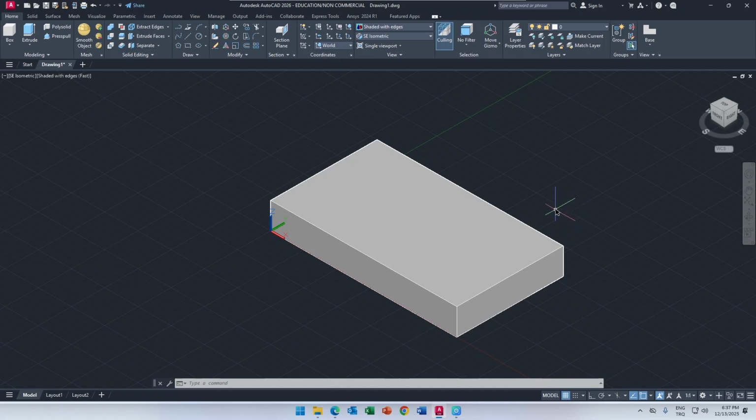So I will create a circle here and a hole. I want to select my line and hover over the top face and go from here 15 and go here 15, but to do it well I can open the ortho mode and clearly set my location 15 and 50 millimeter, and I have reached my location.